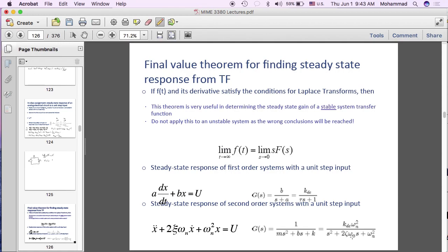We talked about the final value theorem a couple of times, and essentially we said if you want to find the step response of a transfer function, just set s equal to 0. But now let's look at it in a more general form. The final value theorem basically gives you the value of a time function if you have its Laplace transform. So if the Laplace transform of f of t is capital F of s, and you have F of s but you don't have f of t, and you really want to know the steady state value of f of t,